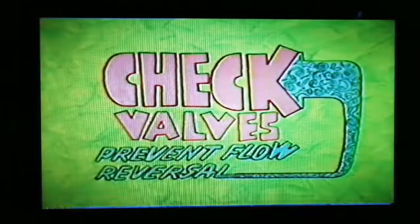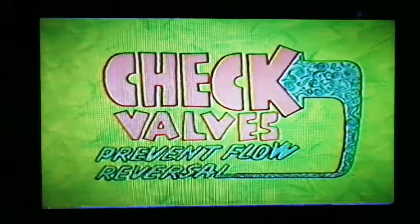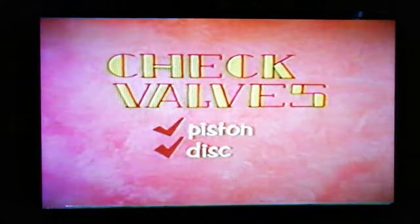Check valves, or non-return valves, as these names imply, are designed to prevent reversal of flow through a line. Reversal must be promptly and effectively halted, or tanks overflow, rotating equipment overspeeds, and machinery is possibly damaged. All check valves fall into two basic types, piston and disc.